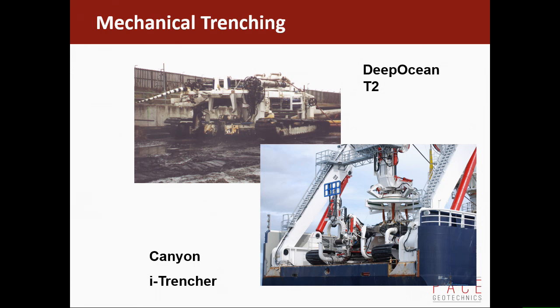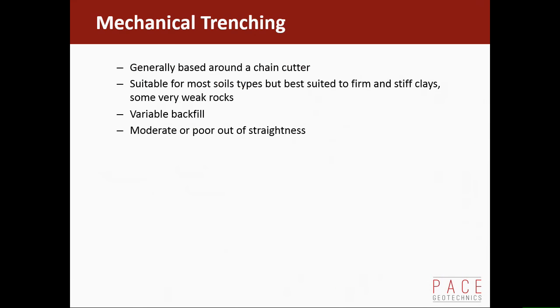And there's a chain in the middle, and it cuts a vertically sided trench in the seabed soils, and the pipeline goes down into it. The disadvantage with those is that you get little or no backfill. You've got to do something else for backfill, really, because the soil is often dispersed.